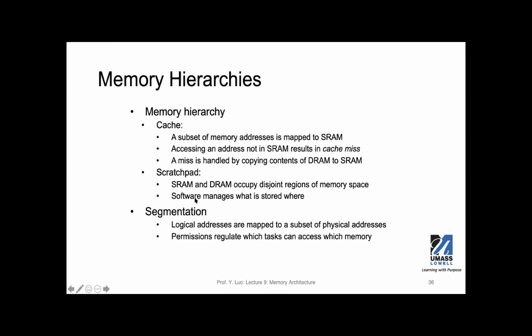And for cache, you don't really have to manage it. It's built into the microprocessor chip. Its addressing, its invalidation, or copying data from DRAM to cache if it is not there, all these are done by the microprocessor hardware, the chip itself. Whereas scratchpad is essentially a small but fast memory space that your software can use. So your software manages what is stored there.